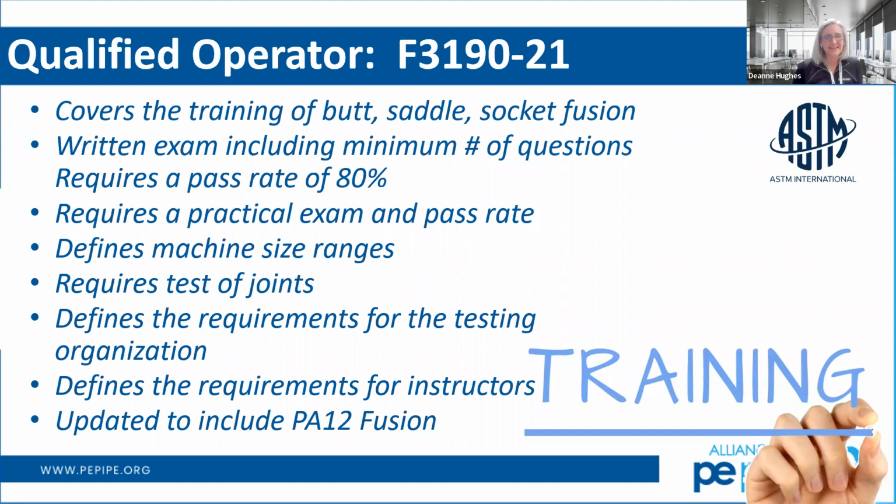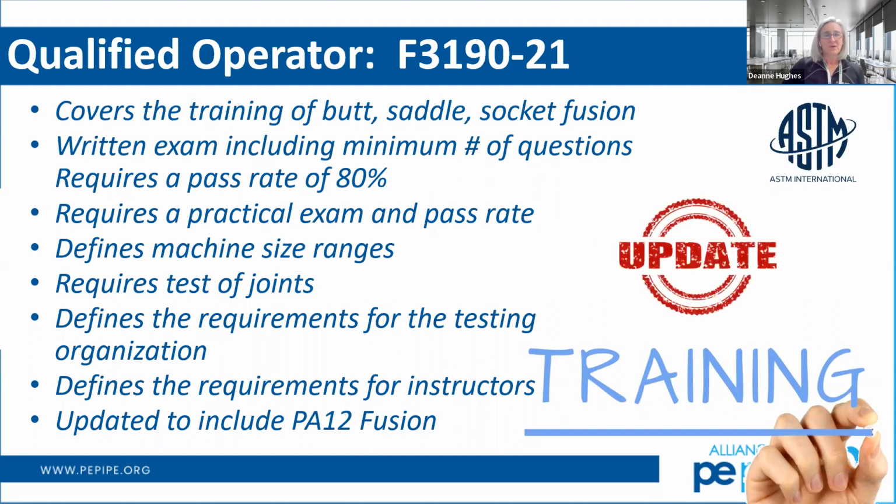It requires a written exam, a practical exam. You actually have to make fusions, and those fusions are destructively tested to be sure that you really do know how to make a fusion. So F3190 is a great place, especially if you're writing specifications, to think about incorporating 3190 as your requirement for those operators who are building systems within your infrastructure and within your municipality. And that was, of course, updated recently.